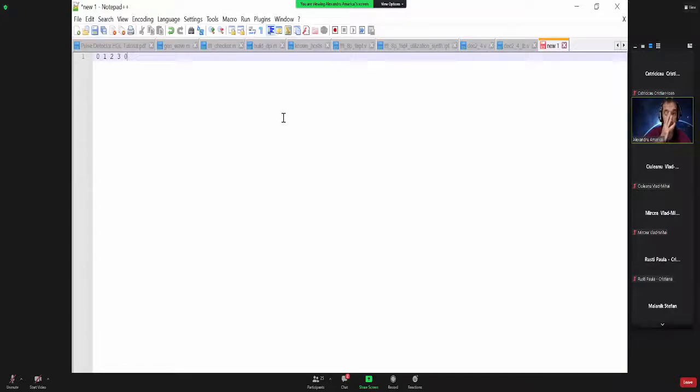Okay, so in this very simple example of the counter, you know the following state based on the current state. So basically, if you are in state 1, you will enter state 2. If you are in state 2, you will enter state 3, and so on, okay? So this is how the memory thing works in these sequential circuits and characterizes the sequential circuits.